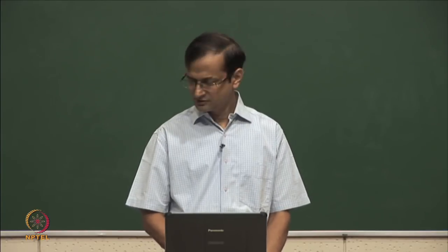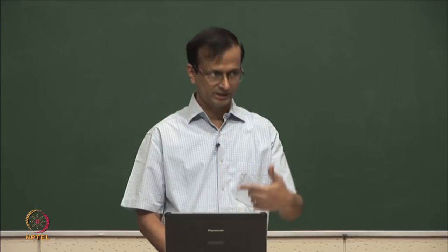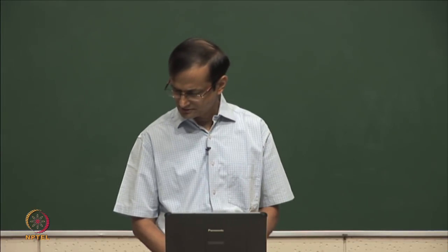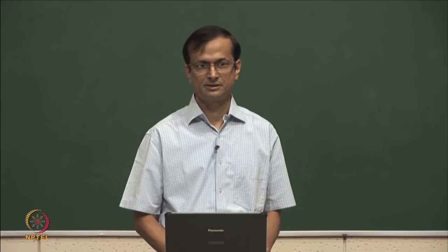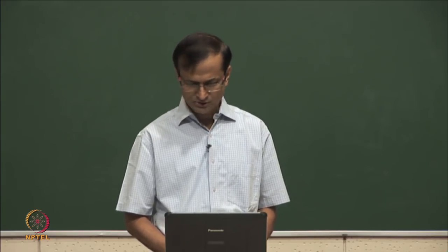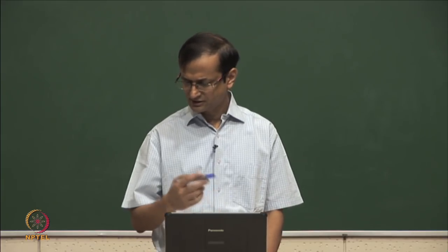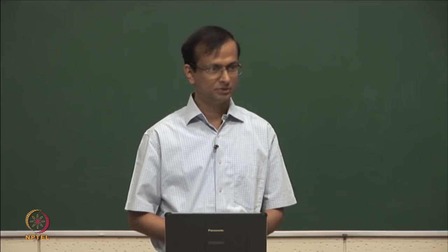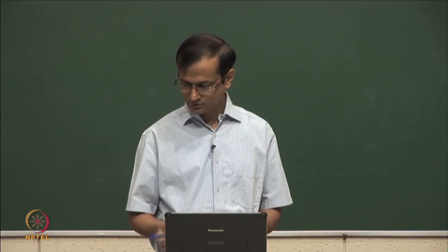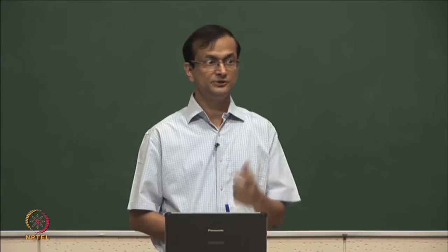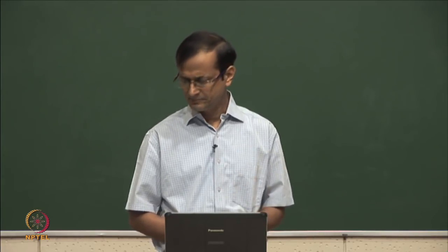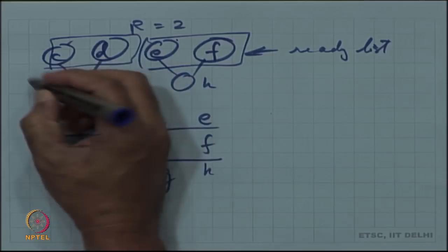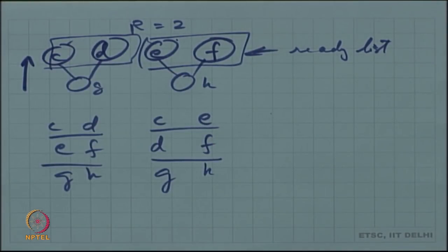But in general, even though it seems as though we ought to take the successors into account, a simple heuristic might not be there. What is often used is just this thing of height of the nodes going from the bottom. Here we did not, so this priority computation was the difference between ASAP and ALAP. You could take the height instead. This has some different implications, although both are intuitively similar.